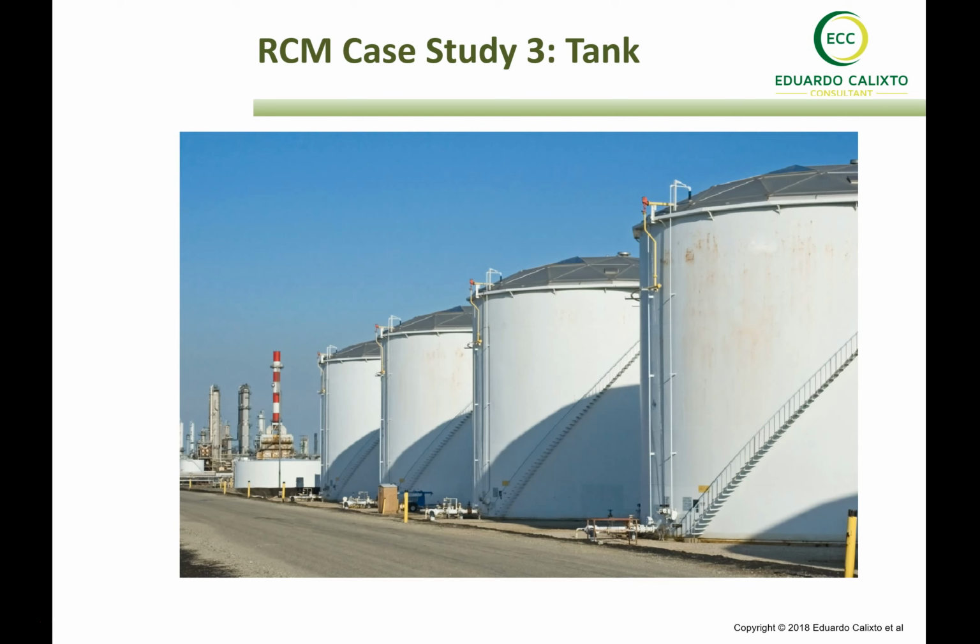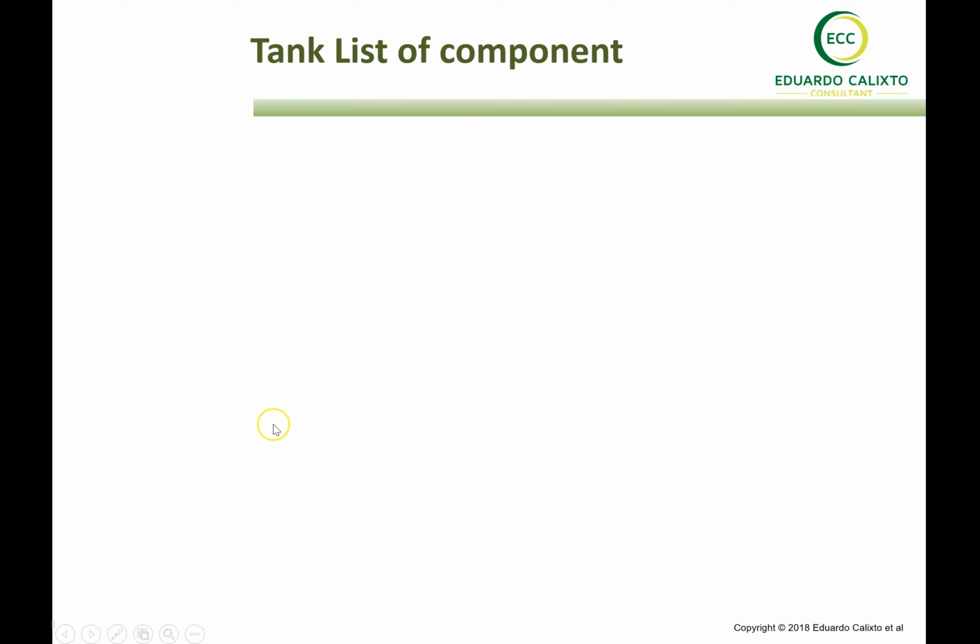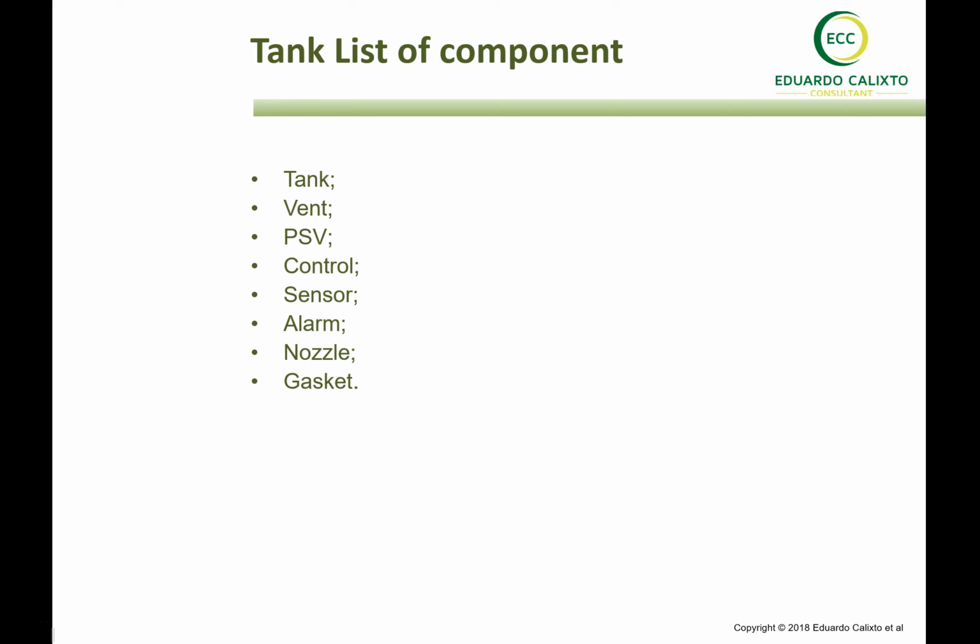So usually for integrity safety related issues, risk based inspection is a technique that is very similar to RCM when carried out during the design phase. That is the most appropriate one to define the integrity problem. But of course, during the RCM, we can define many predictive maintenance non-destructive tests, similar ones that will avoid or detect the integrity problem.